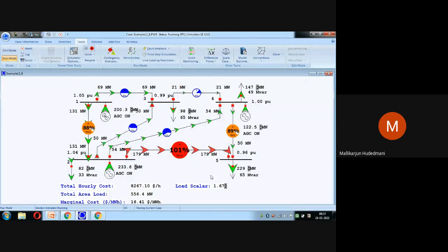When AGC is on, automatically all the generators interconnected to the system start responding in proportion to their capacity and characteristics as per the disturbance or load considered. You may ask me, if the load decrement occurs, naturally automatic decrement on each generation should take place till the capacity of their generation is considered. This is how control works when I have AGC on, I can show you.